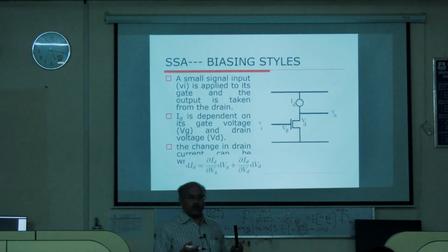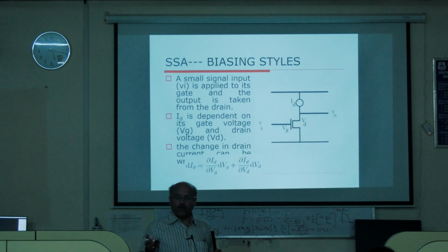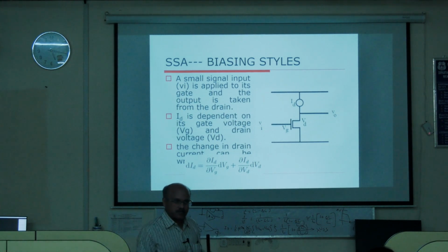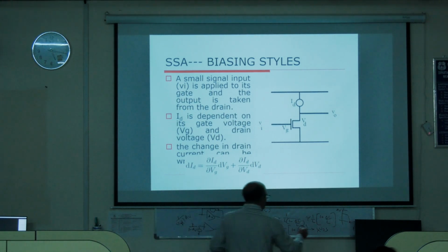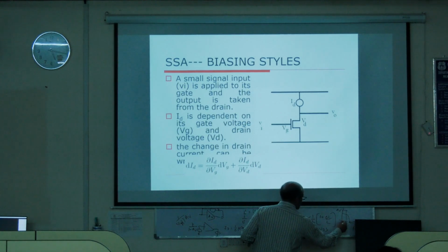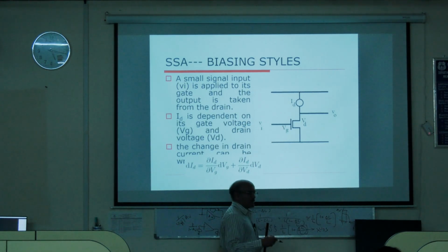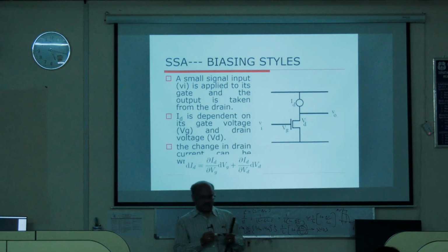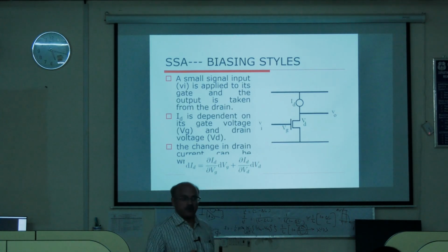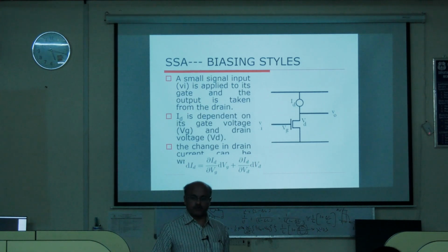Therefore the corresponding pole moves towards the origin, so the unity gain frequency is coming closer to the origin. The available gain bandwidth is decreasing. So the larger the gain, the smaller the bandwidth. Therefore for this given technology I can't improve anymore.